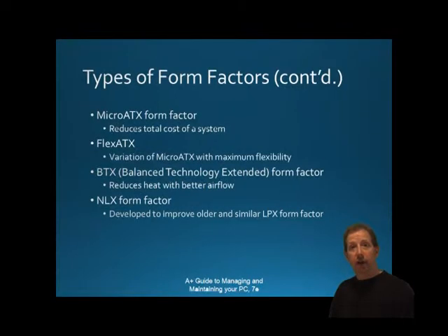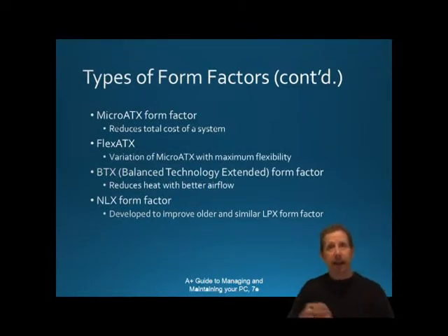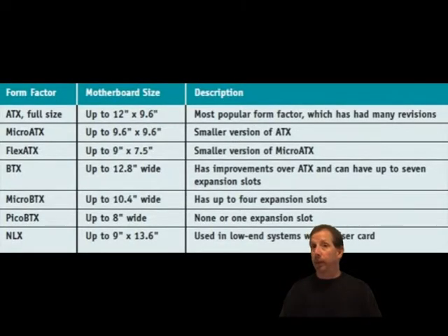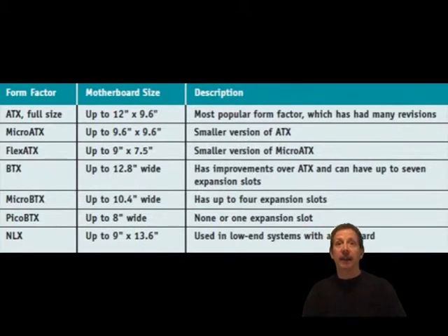The first one I want to discuss with you is the ATX form factor. ATX stands for Advanced Technology Extended. It is the most commonly used form factor today. It is an open, non-proprietary industry specification originally designed by Intel in 1995 and has undergone several revisions since then. An ATX motherboard measures up to 12 inches by 9.6 inches. The CPU and memory slots sit beside expansion slots so that full-length expansion cards don't bump into the CPU or memory modules. The original ATX form factor had case fans blowing air into the case, but later revisions of the form factor had fans blowing air out of the case.